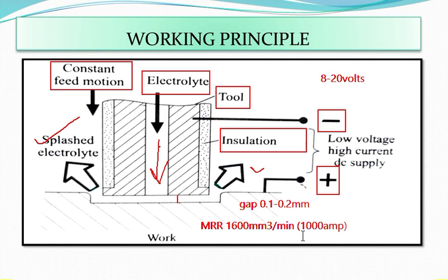Approximately 3 kilowatt hour are needed for removal of 16,000 millimeter cube of metal, which is almost 30 times the energy required in a conventional machining process.